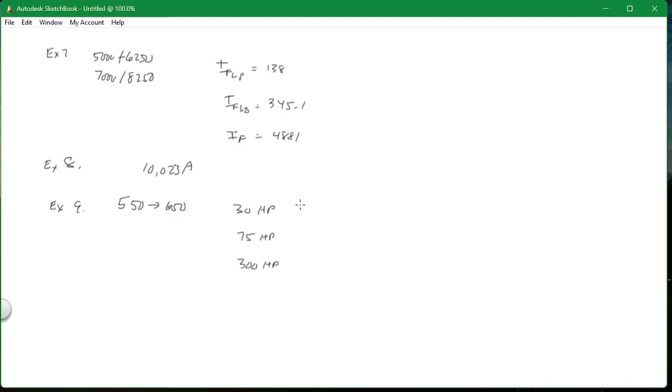And I got 1.42% dip there. I got 3.78% there, and I got a 14.17% dip there. Number 10, we went from 500, that was his example, and I went to 600. And my number there is 156 kVAR that you have to add. How you add that is up to you. 156. Okay. So that's as far as I went.